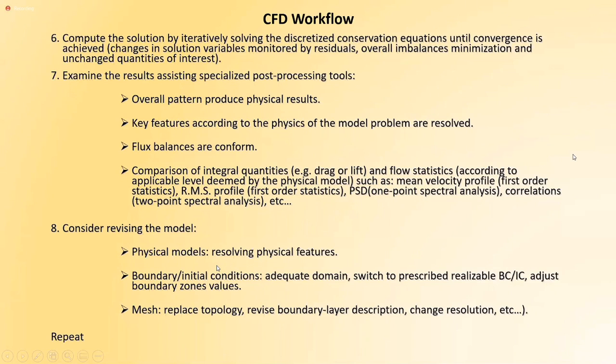First of all, sometimes checking different ways to model the same thing might be a good idea. Usually in RANS, what we do is what is called a mesh independence procedure, which means that we refine the mesh and check. We have some kind of a rule: 5% of change is good enough for me, and then I can take the solution as the right solution.